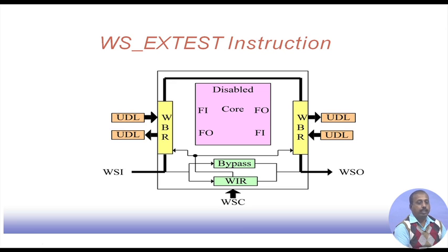It does not have any input pin or output pin that can be connected to the parallel interface or serial interface like that. But it is a small piece of circuit which is close to some core. So, through this WSI line we send the test patterns that can be used for testing this UDL. Now, normally whatever we shift in through WSI is going to be a test pattern for the core, but in this case this is put in the X test mode.